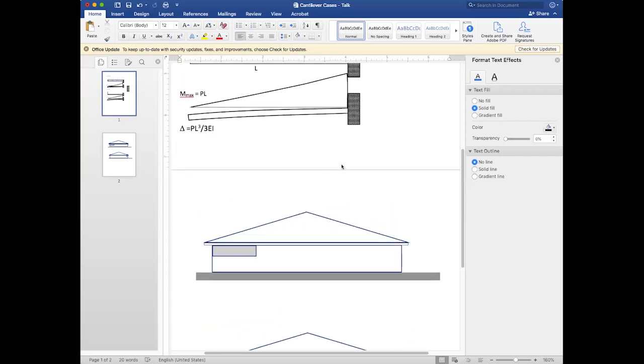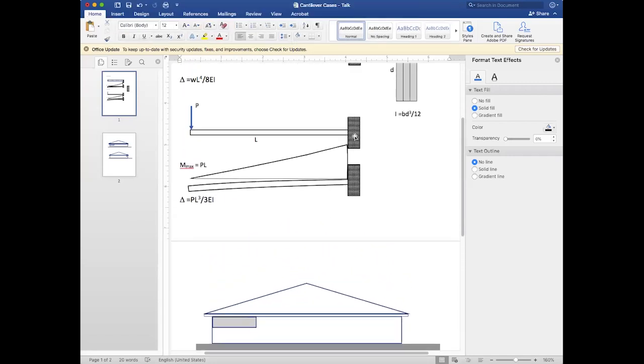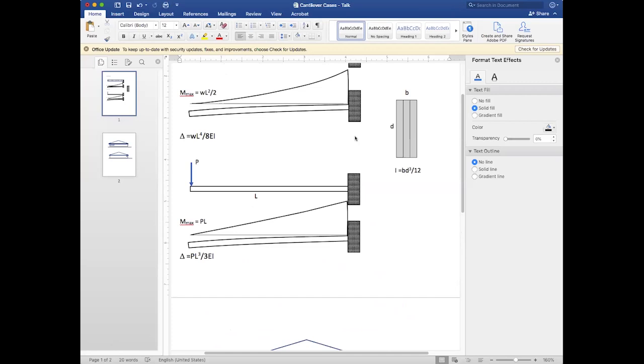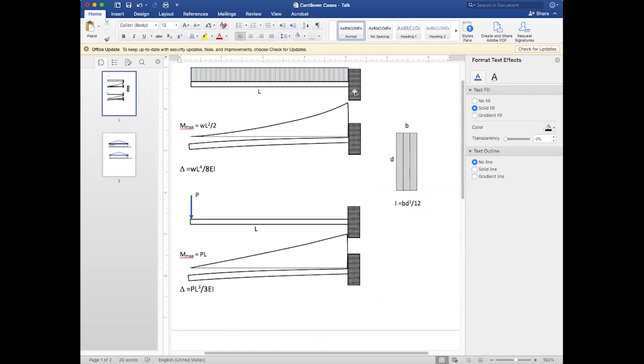And that's so that to make a rigid connection at the end in timber is extremely hard. If I had put, for example, a 12-foot length, I don't know of a connection that you can make at this right-hand side of the beam that would be rigid enough and not deflect or actually lever out of level.